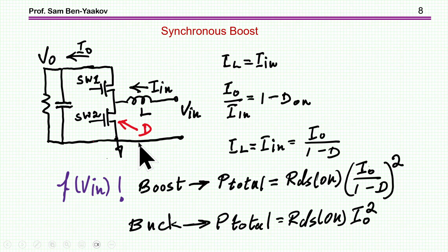And the reason is that for a given output current at a high duty cycle, the current of the inductor is much larger than the output due to this relationship of the duty cycle here. So the story here is really different.